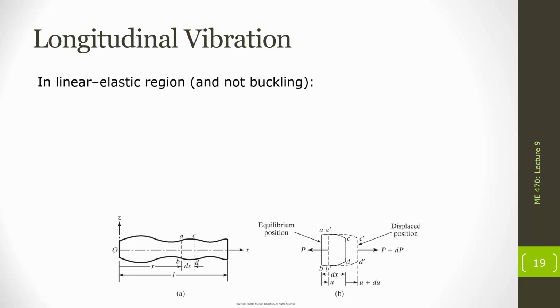Drawing back from strength of materials, we know that when this is the case in the linear elastic region, we can relate that internal normal force P to the stress in our material. That it's typically P over A equals sigma, our internal normal stress. But here I've expanded out and said that P is sigma times A. And we know materials property-wise that there's a relationship between the normal stress in the material and the normal strain in the material, epsilon.